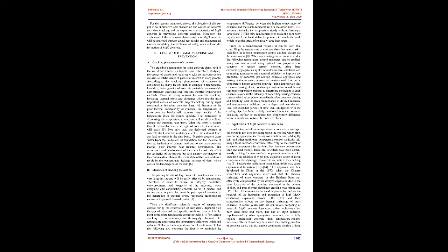Not only that, the deformed volume of concrete itself and the inhibitory effect of the external force can lead to cracks in the dam body. Massive concrete dams suffer from the limitations of foundation and the increase of thermal hydration of cement, and due to the mass concrete masses, poor internal heat transfer performance. The occurrence and development of these cracks not only affect the aesthetics of the project, but also destroy the integrity of the concrete dam, change the stress state of the dam, and even result in the concentrated leakage passage of the dam, which causes hidden dangers for the dam.